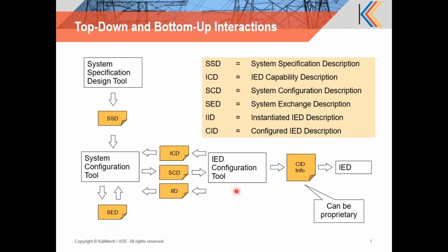Very technically speaking, the concept of IID file was not created to satisfy a role where everything is done at the IED configuration tool and imported back to an SCT, system configuration tool. The concept of IID was generated as a natural part of the top-down flow, except that it's in the reverse direction. That means in the top-down flow, once you have finished configuring and instantiating all the IEDs in the station, there are many use cases where you may require some local re-engineering of the IED using the IED configuration tool. Now, if you perform a local re-engineering here, and if you try to export an ICD file, you're back to